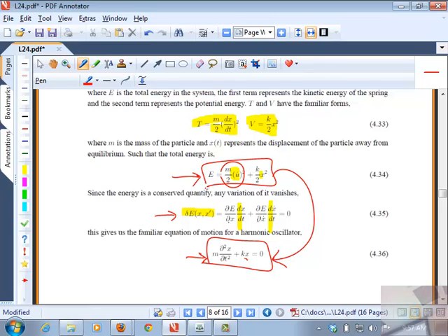So the m cancels out, but du/dt is the same as d squared x/dt squared, because u is dx/dt, right? So if I didn't know anything about the energy, I could write this equation by making a momentum balance, right? So this is Newton's law. Mass times the acceleration is equal to the sum of the external forces. And the external force here is only the spring, right? So without knowing anything about the energy, I could write this down from a force balance point of view.